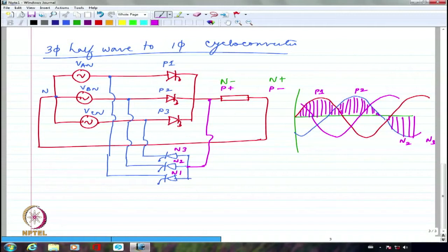So it's very important in a cycloconverter to sense the current. Without current sensing, you cannot release the firing pulses to the other set of converter. Otherwise, you will have a dead short circuit. You will have a big problem with the connection of the two converters, because you are trying to connect completely opposite polarity together. That's the reason.